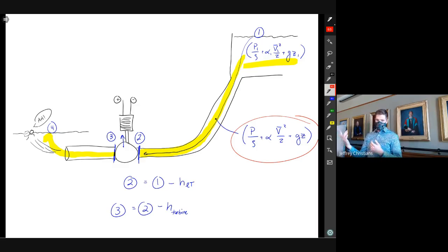So for example, the minor loss coefficients, the K values, you look those up in tables. What if you multiplied it by a factor of 2? What happens? Does essentially nothing change? Or do we see a little bit of a change, or do we see that it actually changed our final efficiency by 10% or 5%? That's a big deal, 5%. We really have to key in and make sure we're designing our system with the lowest possible minor losses.